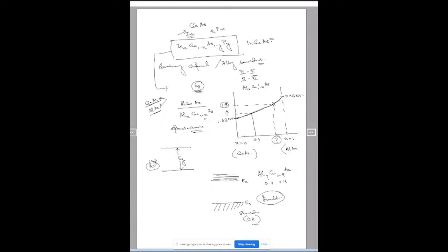But when you take this to a certain temperature, say room temperature, 300 Kelvin, we'll find that some of the electrons will gain energy and move to the conduction band. Once they reach the conduction band, they find a lot of allowed states. Allowed states are required for the electrons to move when you apply an electric field. So a good number of electrons will come into the conduction band.